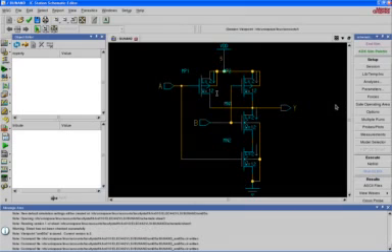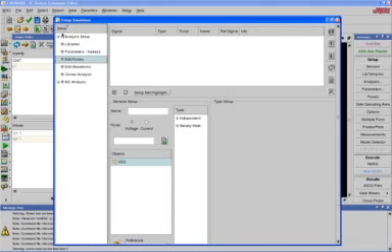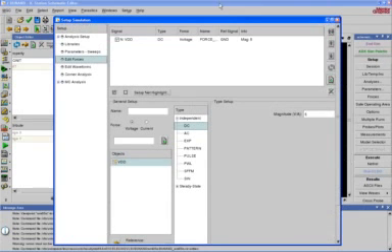Now we need to set up the forces. So let's start out by defining the VDD as being 5 volts. Highlight that. Click on forces, manager. This brings up a setup simulation window. So let's set up the forces first. We'll call VDD selected. Click on independent source, DC. We'll set up VDD of 5 volts. Okay. Click on the add button. Let's go back.